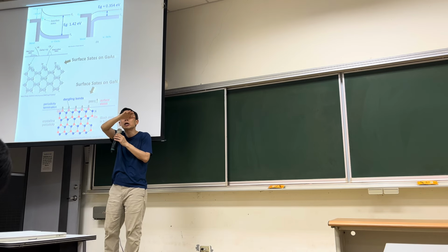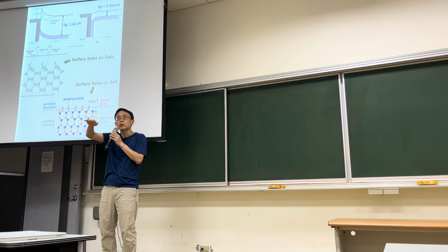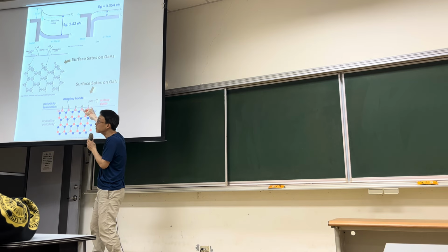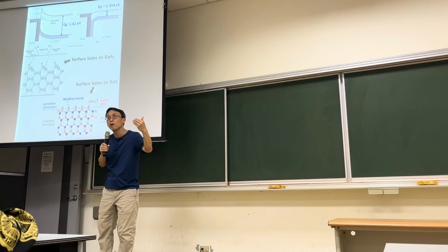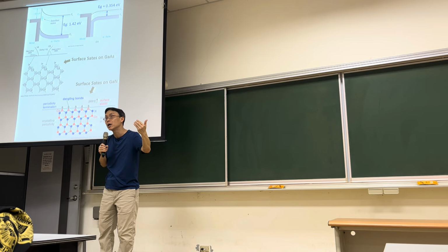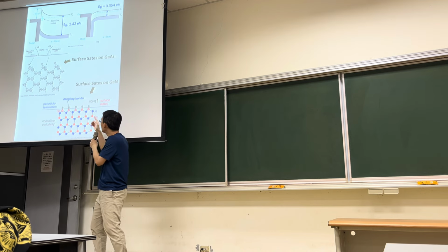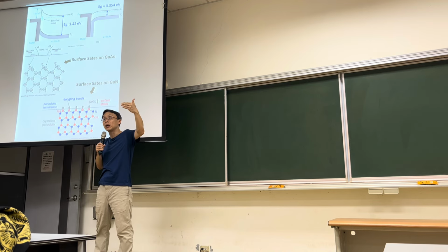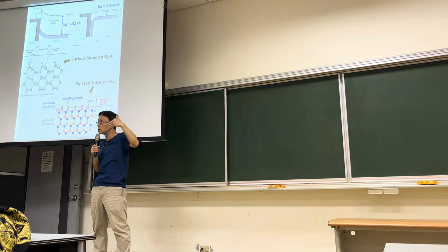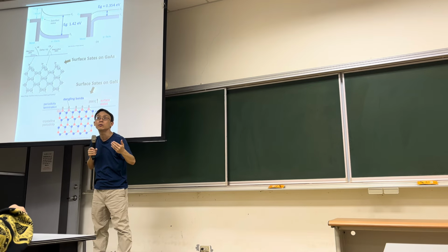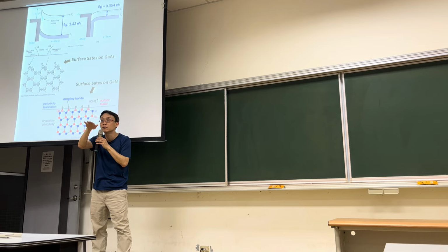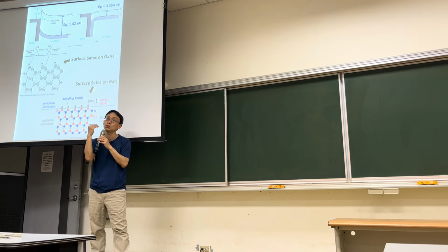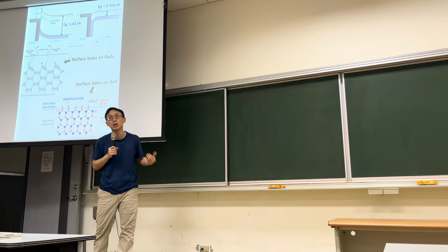But on the top layer of atoms, because you have nothing above the surface, the valence electrons are not forming covalent bonds with any atoms. In this case, these reactive valence electrons are highly likely to react with the impurities in the air, which will result in a high density of surface states or high charge density on the surface. This is the reason for you to have surface pinning.